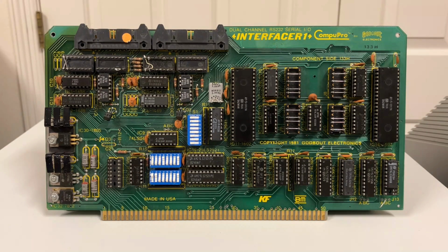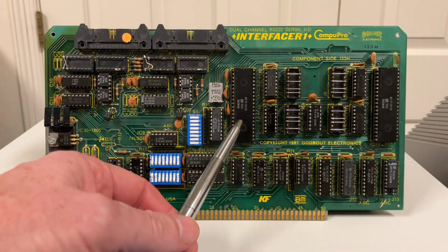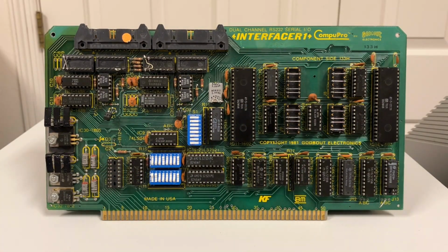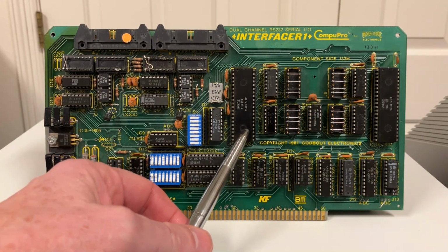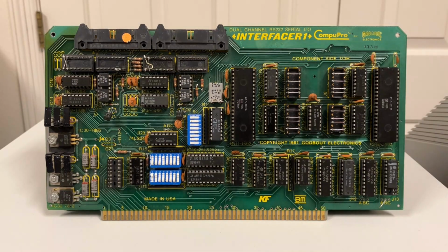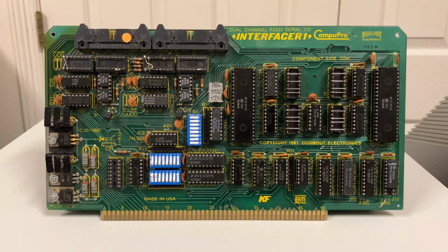And I'm going to use one of these serial ports to be our cassette, of course. I'm going to use this one, which is port B. The first port, I'm going to use that to look like an 88-2 SIO serial board of Altair's, because the 88-2 SIO was by far the most common console port that was used. And I can do that because the 2 SIO was up at 10 hex, which is 16 decimal. Cassettes down at 6, those are not consecutive. However, since we can separately address them, I can do that. And at the end of this video, the end of this section, I'll show you how we make that serial port work for the console.